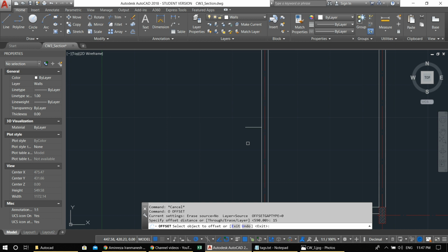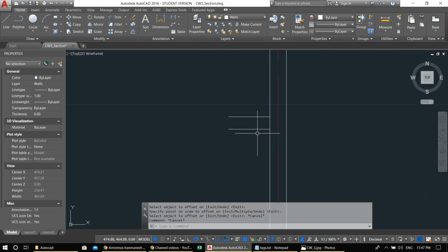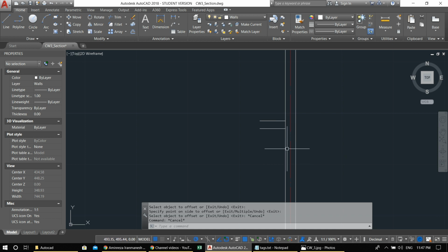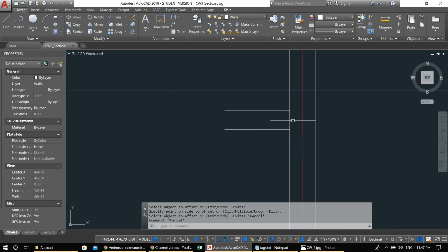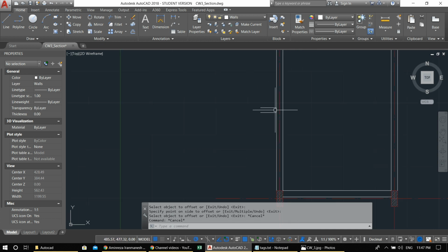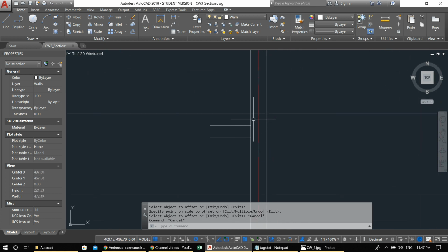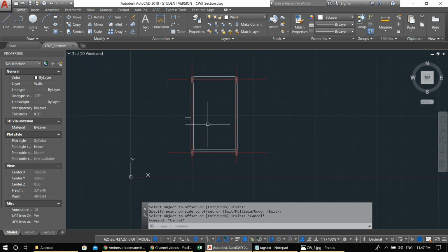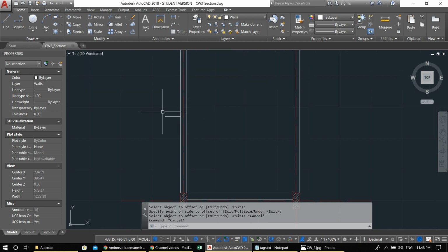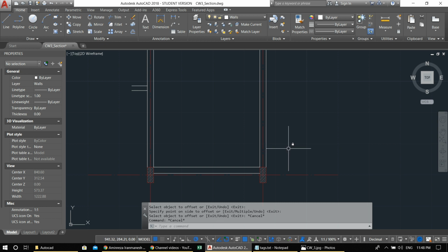Offset 15. Depends on your type of drawing, and usually, because this might be a shear wall, there might be a line here. You don't always have to remove the line. If this is a shear wall, and this is basically a kind of 1/20, we might keep this line here. We will have our break line later in the annotation.